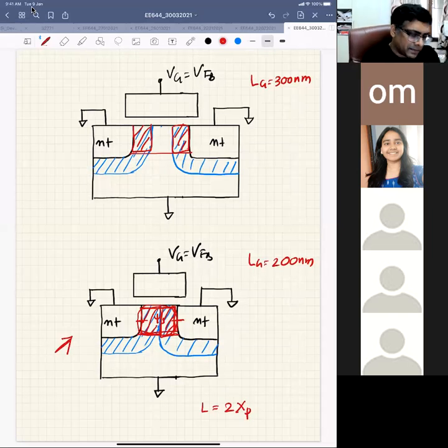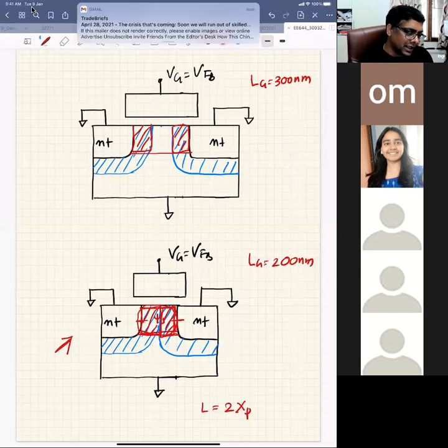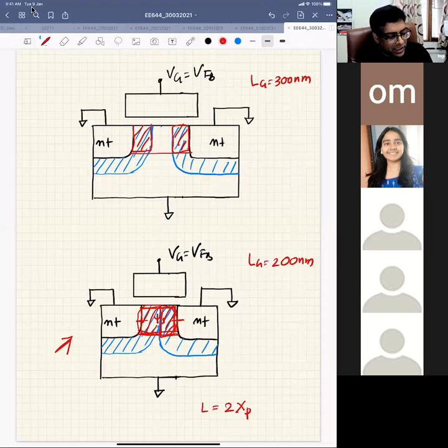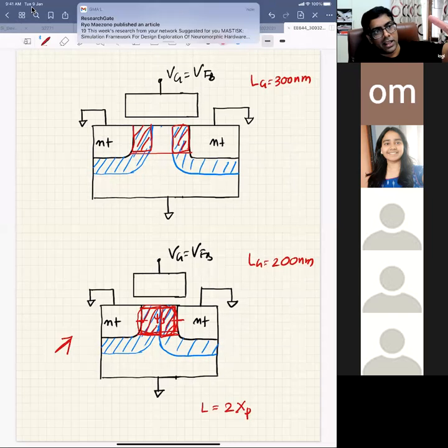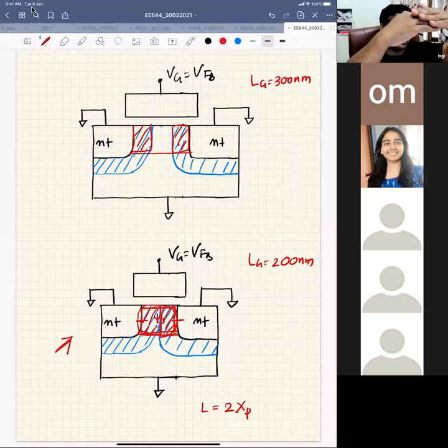So, sir, it will be in proportion to the thickness of the oxide and depletion there. Yeah. So you only think of it in this way, right? When you're applying some gate voltage, before you apply it, there are already some charges available, right? And these charges will also contribute to invert your channel. That means you need to apply less gate voltage, because source and drain are also contributing to the total charge in the silicon, right?